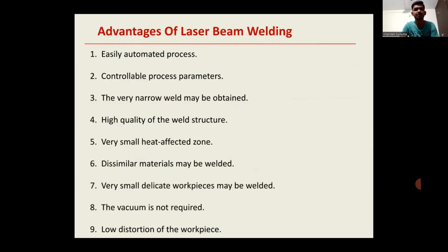Advantages of laser beam welding: easily automated process, controllable process parameters, very narrow welds may be obtained, high quality of weld structure, very small heat affected zone, dissimilar materials may be welded, very small delicate workpieces may be welded, a vacuum is not required, low distortion of the workpiece.